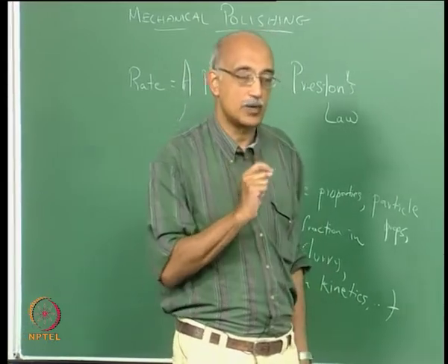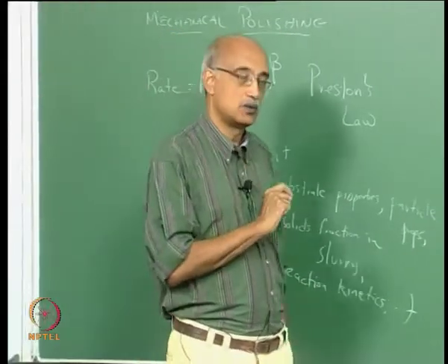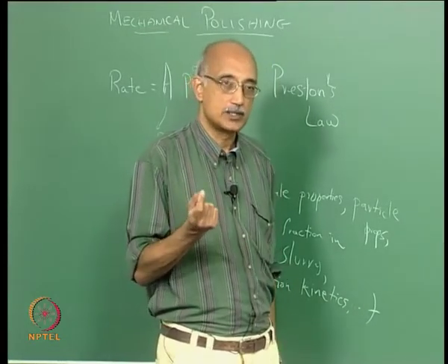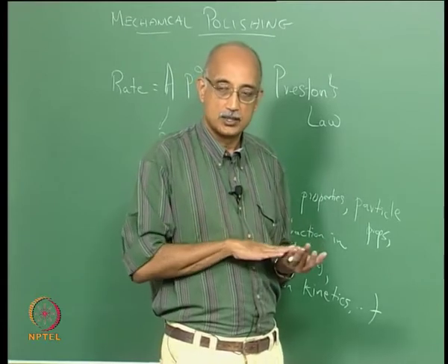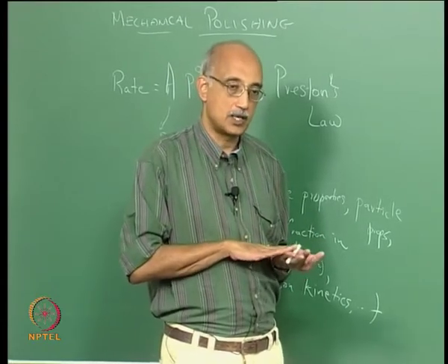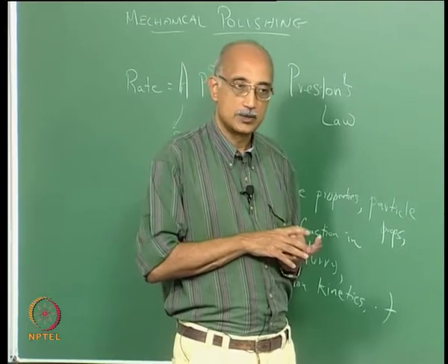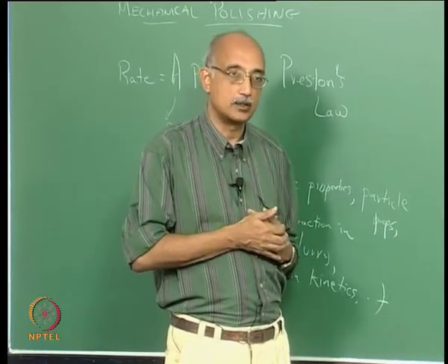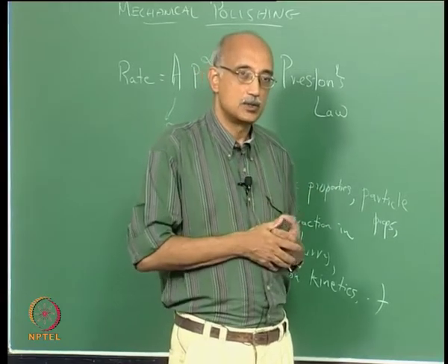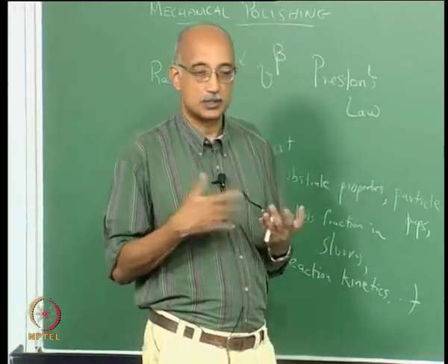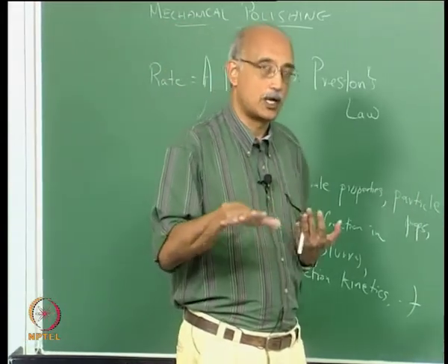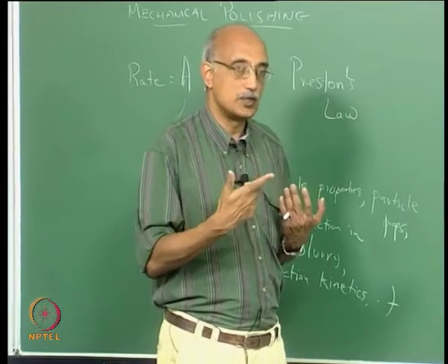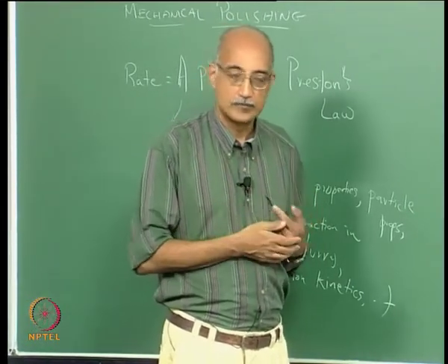A more crystalline particle is more likely to give you higher removal rates, but that will change over time, because as you keep polishing, the polishing media itself will start changing shape, and so you will start essentially truncating the elongated shape of the abrading particle. It will become more rounded. So, the kinetics of surface material removal will actually slow down when you start using a non-spherical slurry to begin with, which through reuse becomes more and more rounded.